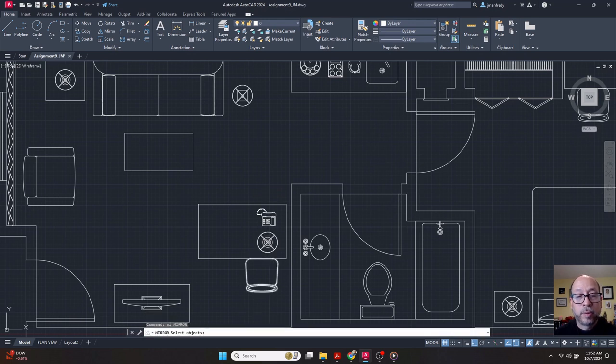Then I'll mirror it about the center line of this table vertically. And then I will mirror this about the center line of this, drawing a horizontal line. I'm going to flip it to the other side, mirror it there, and enter. And then I can slide it over basically. I'll move it over, let's say 6 inches. Or maybe I'll move it over a foot, 12.